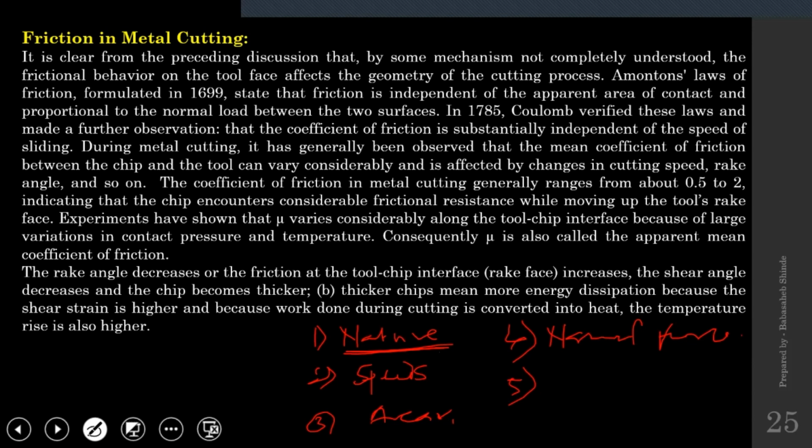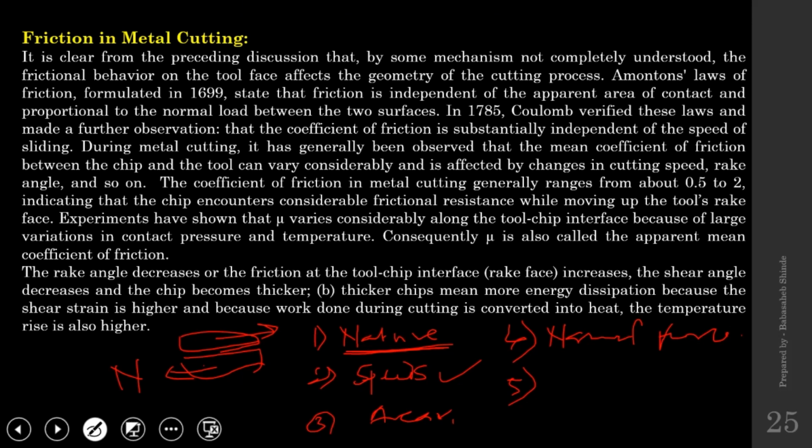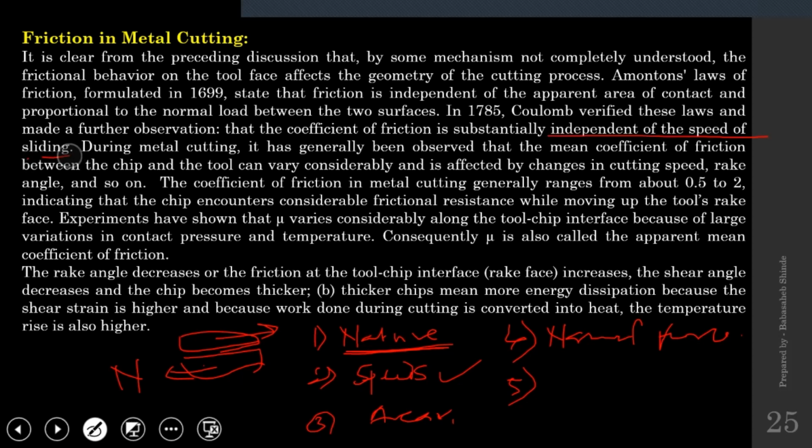Second, speed. Suppose this is one surface and this is another surface, moving in opposite directions. If I increase the speed, what will happen? Will the frictional force increase, decrease, or remain constant? Okay, this frictional force is always independent of the speed of sliding.